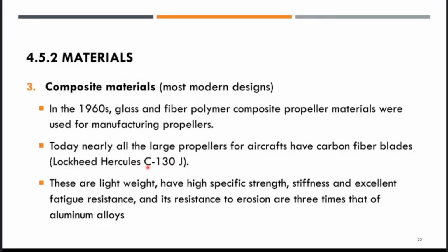These are lightweight compared to wood as well as metal. Composites are lightweight, have high specific strength, high stiffness, and excellent fatigue resistance, and their resistance to erosion is 3 times that of aluminium alloys. That's why no more wood or metal propellers are being used in modern aircraft design for piston as well as turboprop engines.